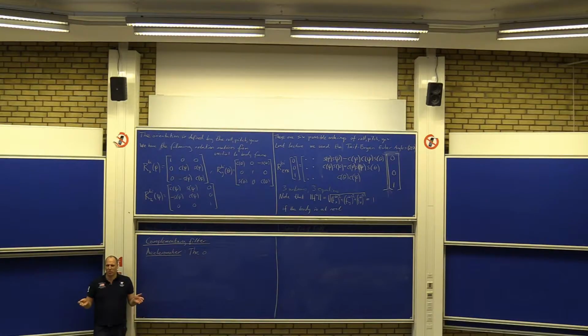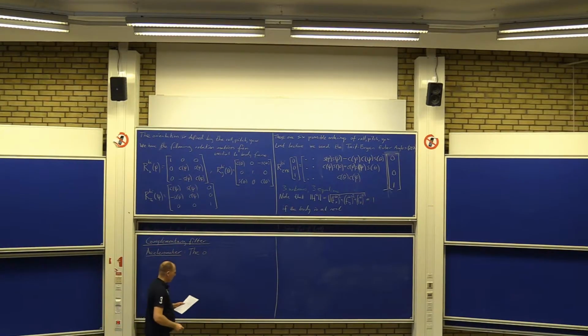The gyro gives us the angular velocity, right? And to get orientation we need to integrate it once. And then, of course, if there is a bias, it will start to add up, and we will get off the correct orientation after some time.